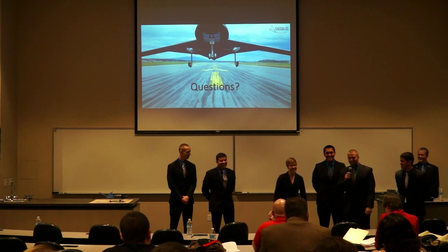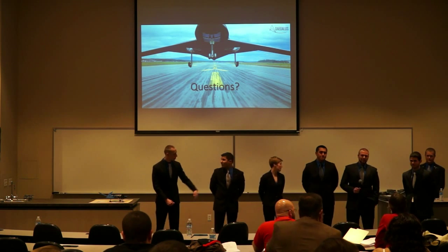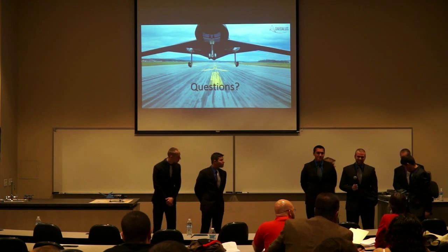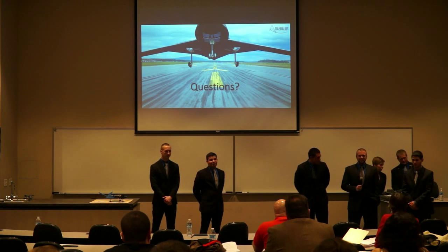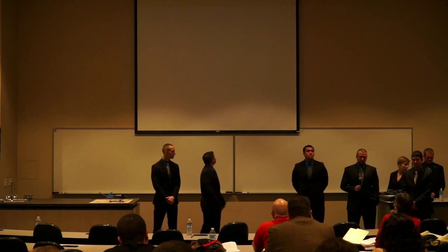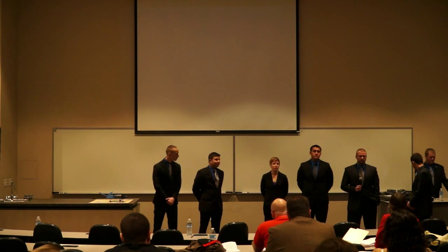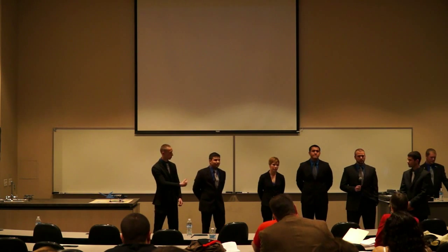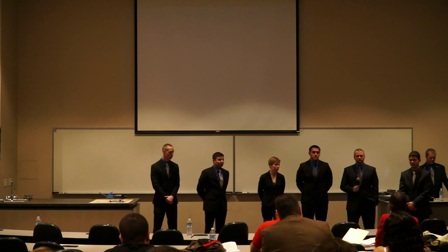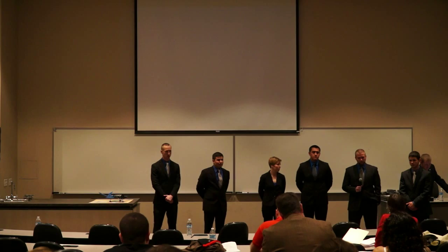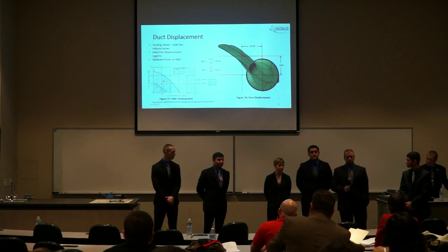Hi, Alex. Very challenging putting what I would consider a high bypass ratio turbofan engine into an embedded design. Your serpentine inlet coming from the top of the aircraft has a little bit of curvature to it. So any idea how you're going to handle the boundary layer buildup on that inlet?